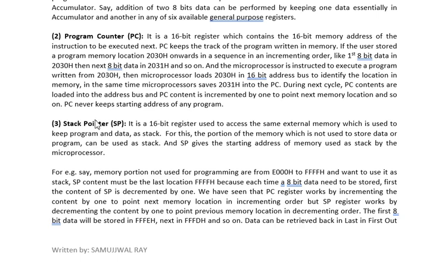Similar to the program counter, we have another 16-bit register which is called the stack pointer, which works upon the stack. Whatever memory is connected with the microprocessor, some part of the memory is used as stack. We'll learn about the stack later on. The stack pointer, which is also a 16-bit register, gives the address of the stack, from which memory location onwards the memory is used as stack.